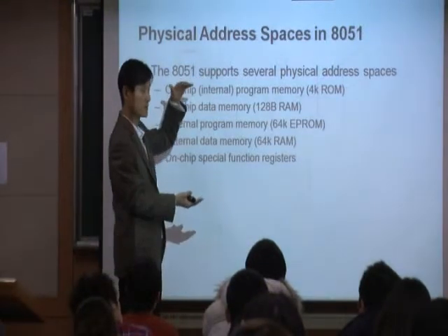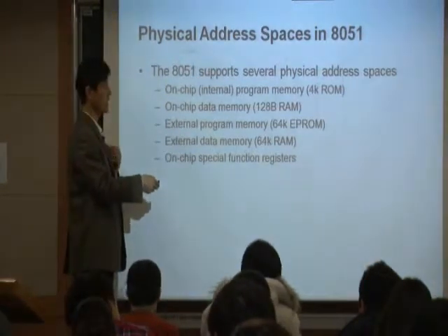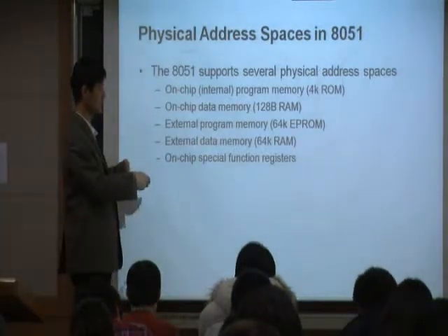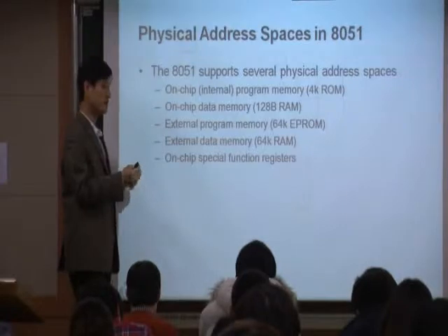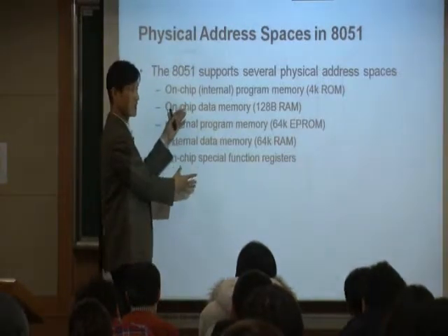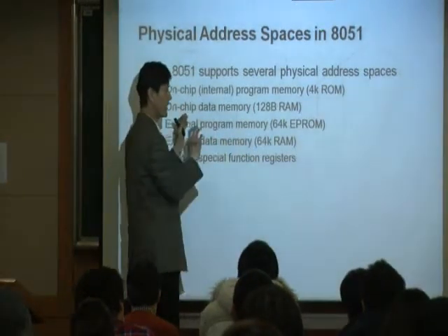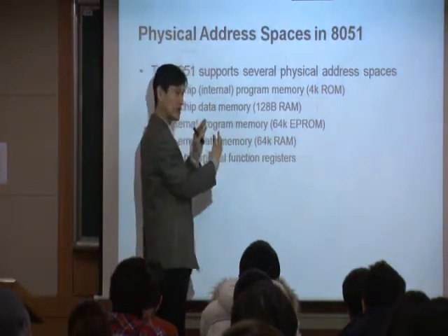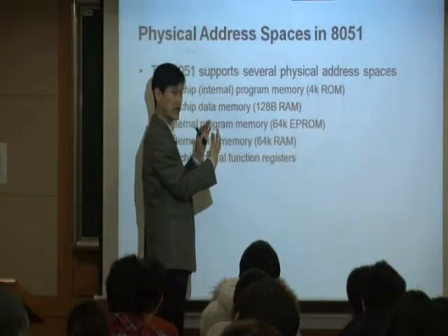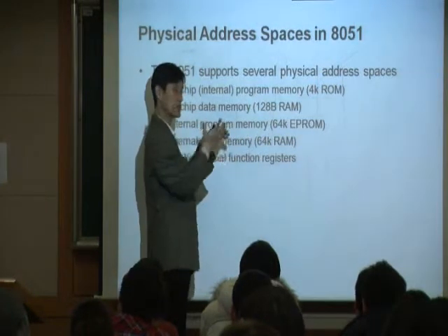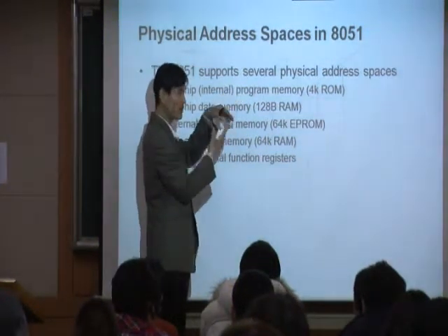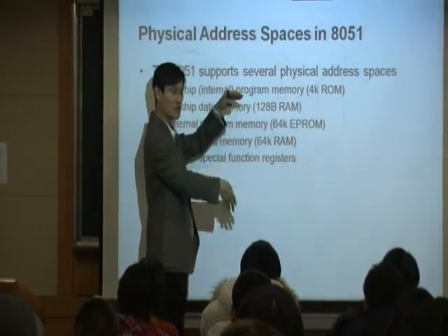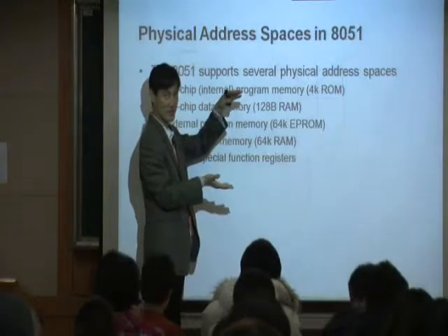the code memory space. We also have another 64K of data memory address. So that's this one. Which basically means that there is a processor here. If you want, then you can buy a 64K memory and connect it to the processor. In that case, the memory is actually 64K and our address space is 64K. So you can take advantage of 100% of address space, right?